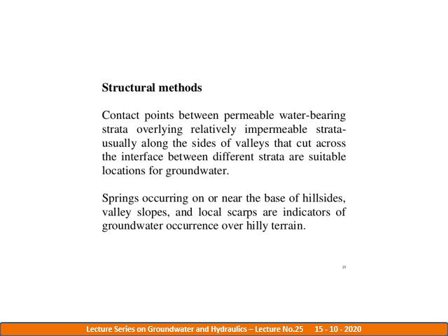In geophysical borewell logging, due to the circulation fluids and the high drilling speed employed in modern drilling techniques, the quality of soil and rock samples is poor. Using geophysical borewell logging, records of the intersected strata can be obtained. The records can be usefully interpreted in terms of subsurface lithology, moisture content and groundwater quality. A logging unit consists of a hoist, recorder and various electrodes or sensors which are lowered in the boreholes.